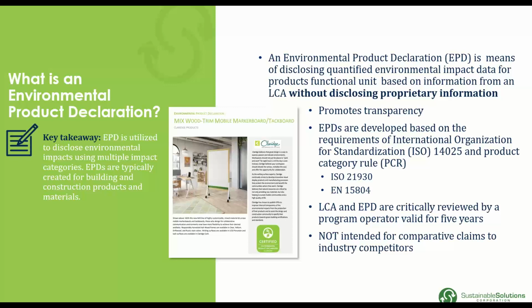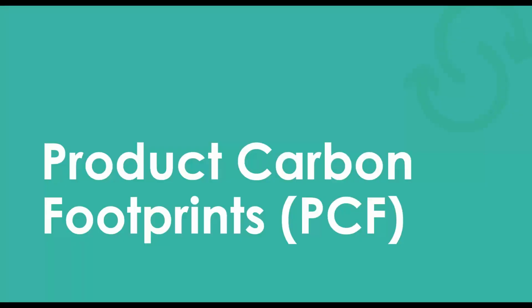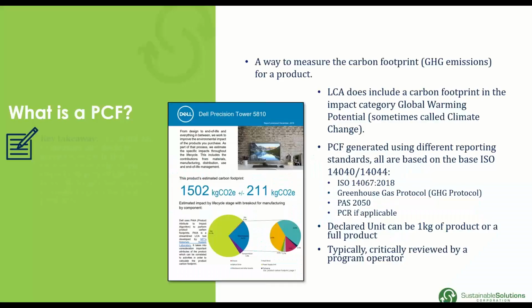And that sets up a whole bunch of different rules on how we run the LCA. And these LCAs and EPDs, once you're going for an EPD, are going to be critically reviewed by a program operator. They're good for 5 years. And these are really not supposed to be for comparative claims against industry competitors. The PCR sets a fair way of doing it, but you're not supposed to really be using these for direct comparisons.